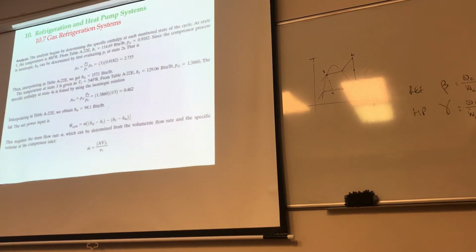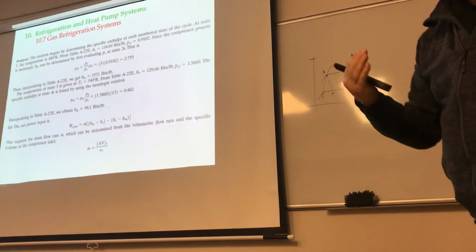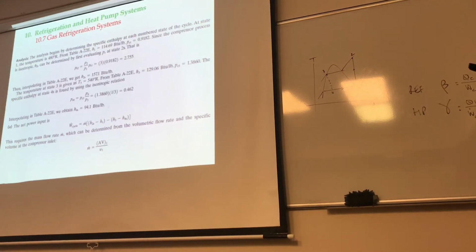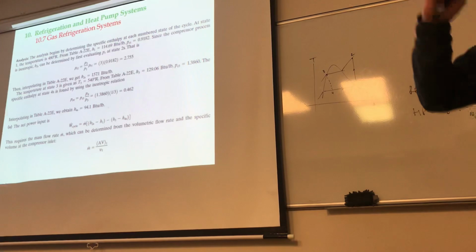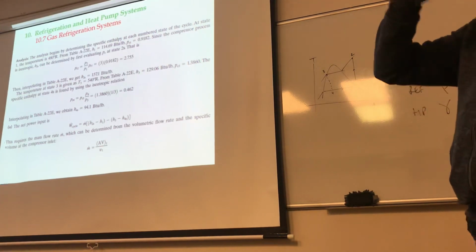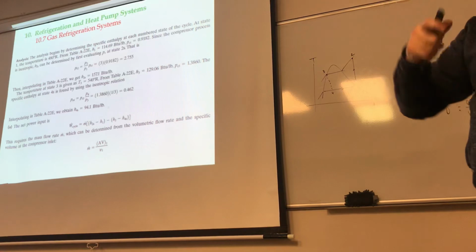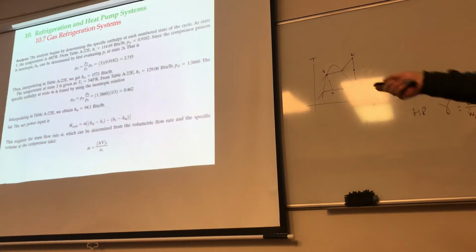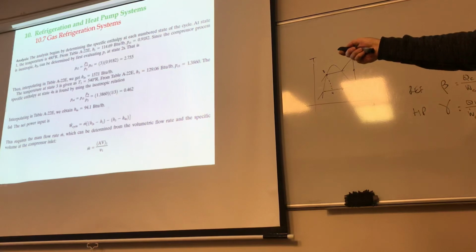And obviously, because it is the start of an isentropic process in this case, we don't read the value of S, but we read the value of the PRs. Remember, when you have volumetric stuff, it's the VRs. When you have the pressure ratios, it's the PRs that you need to read, okay? So we need the value of PR1, which is, remember where it says delta S equal to 0 in that table, that means it's only applicable for isentropic processes, right? So for 480, I read the value of PR1 of 0.9182, which is exactly there.